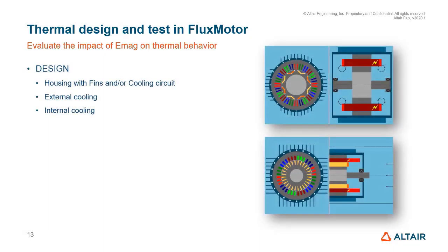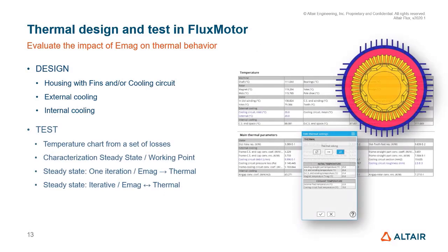So Flux Motor allows you to design different housings with fins and/or cooling circuits and apply different external and internal cooling. And then it allows you to run a steady state thermal test to look at the temperature distribution along the different parts of the motor.